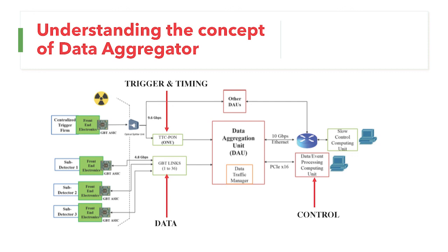And in this part, I am showing you the control signal. Since this is an electronics module, and as you can understand, electronics modules are very flexible and don't hang like computing devices, this control system can directly assert a control signal here. For example, stop the data acquisition immediately because the DAQ has gone down, or the trigger or detector has gone down, or maybe there is a beam dump happening. This control signal is asserted directly here, and you can directly take down the data flow.